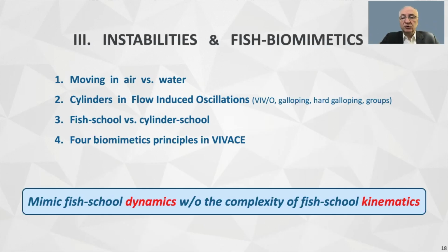Vortex-induced vibrations, galloping, hard galloping, synergistic flow-induced oscillations of multiple cylinders in groups are these kind of instabilities. And there are lots of similarities between the dynamics and kinematics of groups of cylinders or individual cylinders with fish schools or individual fish in forward motion.